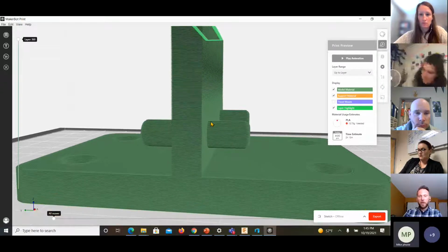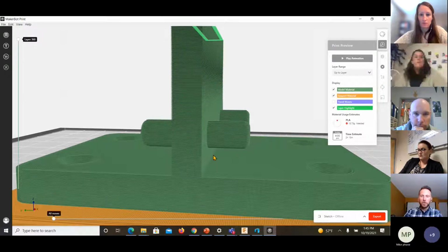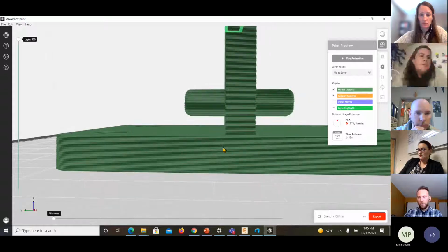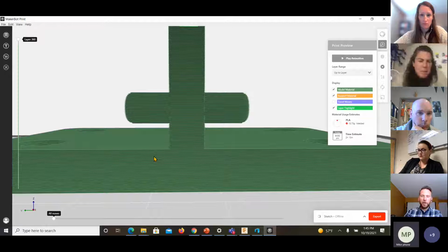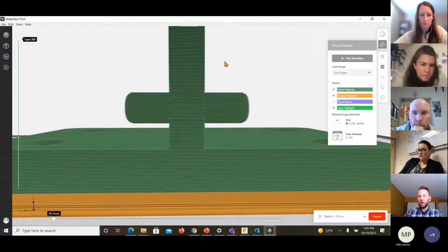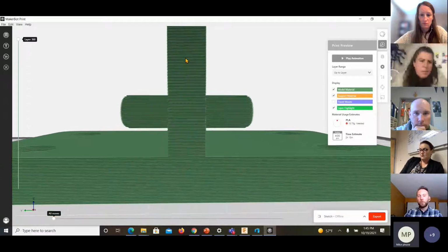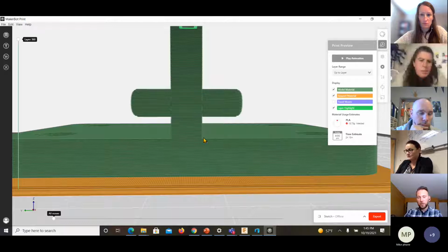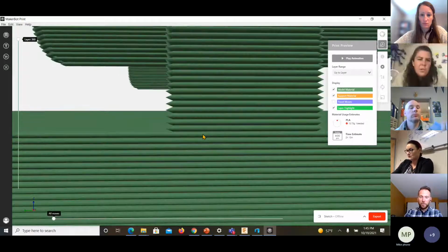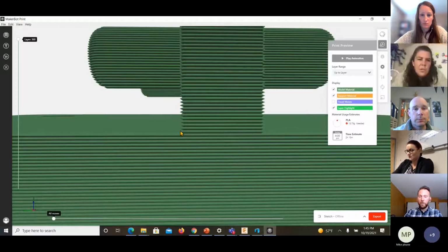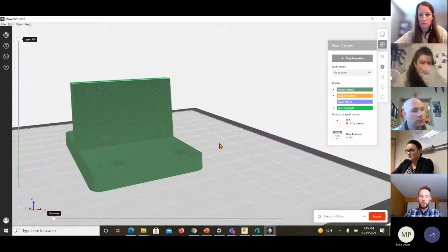And there is a little bit of structural instability when you print something like this, because if you put horizontal pressure on this component here, it would be more liable to break because of this stacking and this hairline right here. Even if we did put a lot of infill in there, the probability is still there.